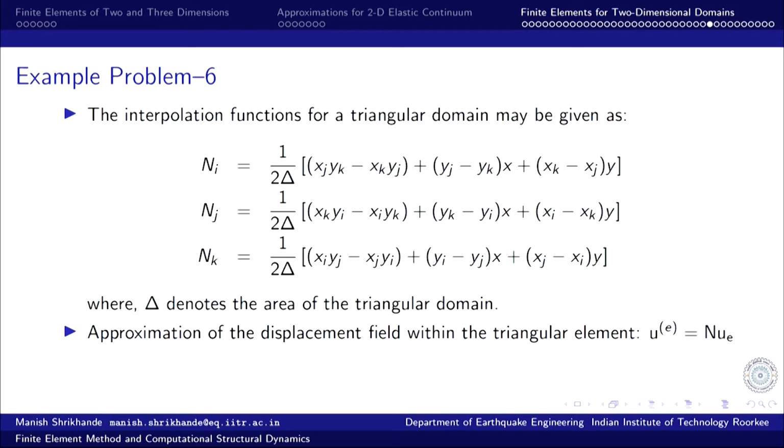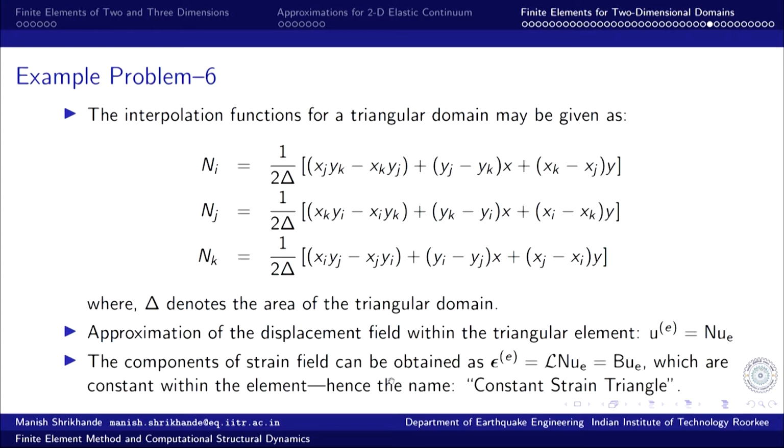So, the approximation of the displacement field within the triangular element is again similarly given by the shape function matrix multiplied by the nodal displacements. The strain field is again the same differential operator operating on the interpolation function, and because all of them are first degree polynomials, the derivatives are constants.